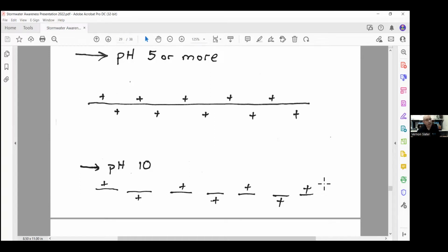I have heard of chitosan referred to as a coagulant, flocculant, and polymer. Which is it? So chitosan is a cationic organic polyelectrolyte that is a polymer and behaves like a coagulant and flocculant. Chitosan by itself will start the coagulation process and continue to form larger settleable masses without the addition of an additional flocculant.